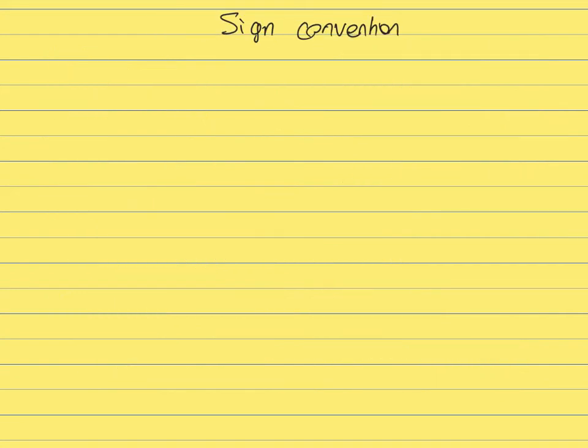So let's discuss a little bit more about why it's important to always define the internal load as pointing towards the outside of the member. For this, let's consider a simple beam like this that is subjected to simply an external load that we are going to write P naught.